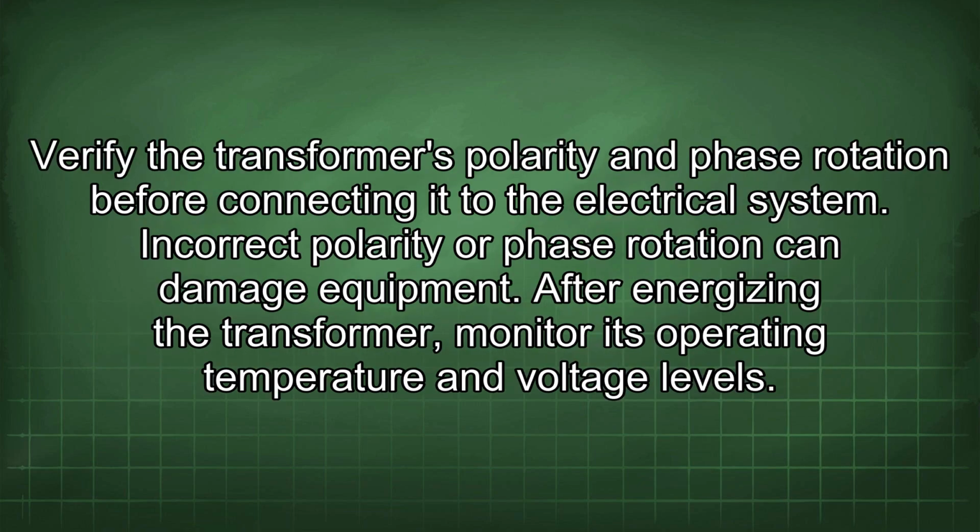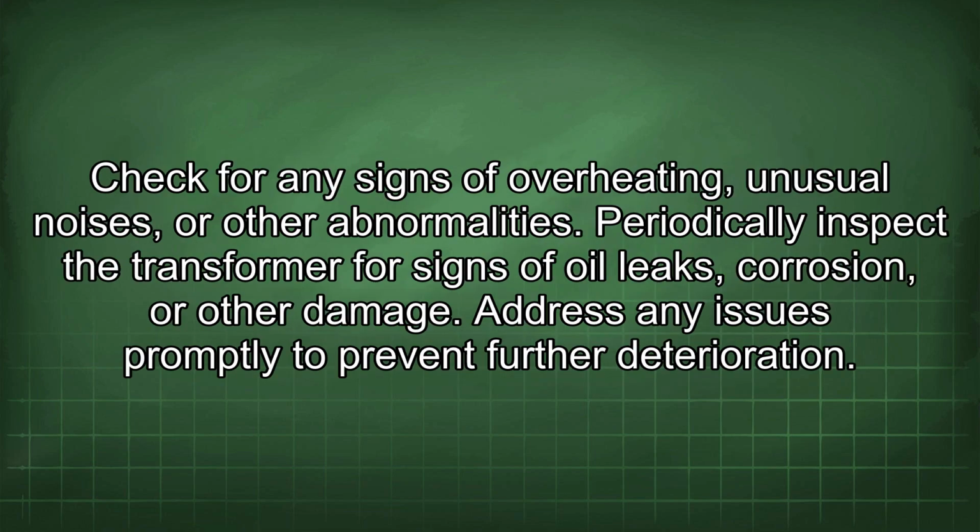Verify the transformer's polarity and phase rotation before connecting it to the electrical system. Incorrect polarity or phase rotation can damage equipment. After energizing the transformer, monitor its operating temperature and voltage levels. Check for any signs of overheating, unusual noises, or other abnormalities.